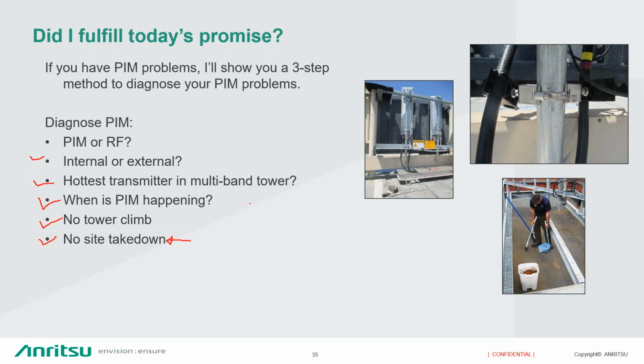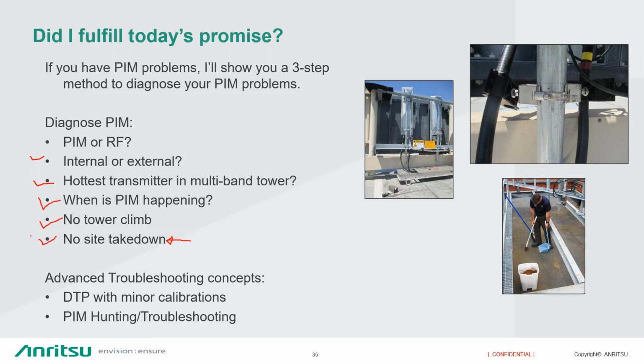And if you do have access to the antenna and you do have access to doing a roof climb, you can do a full distance to PIM calibration so that you can do a distance to PIM analysis. And then I went over some PIM hunting and troubleshooting scenarios that, again, does require a second webinar. Let me know if you are interested in a webinar on some of the PIM hunting, where I combine using data from the IQ FiberMaster with the PIM Master to do a full-blown external PIM analysis and internal PIM analysis if that's where your PIM is.